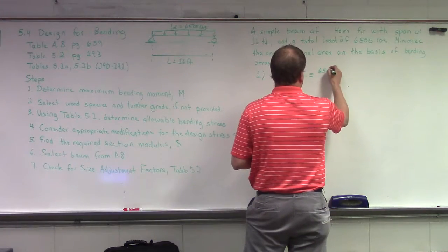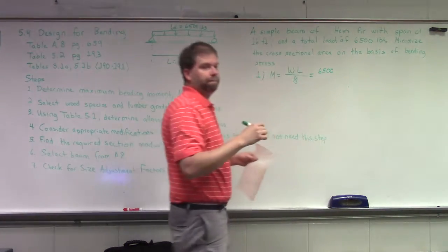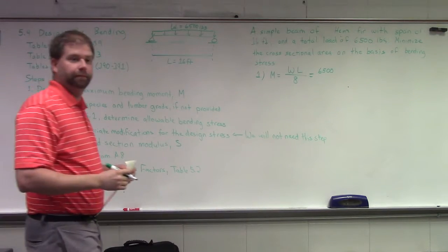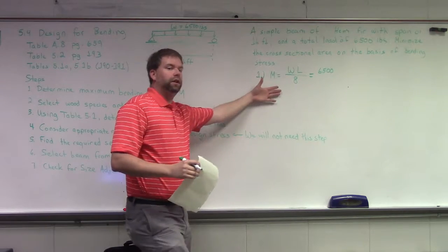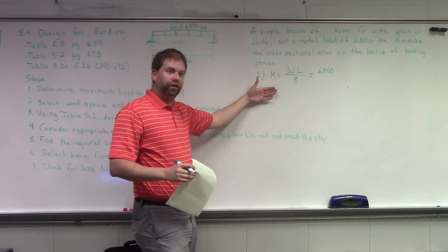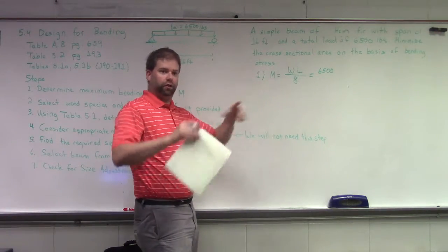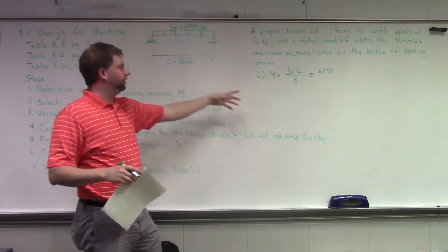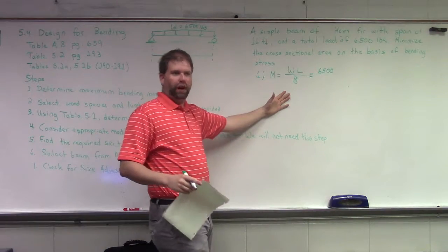Why 8? So if we used calculus in this class, we would derive where this equation comes from. When you take the loading pattern of a uniformly distributed beam and integrate it, your factor out front becomes 1/8.